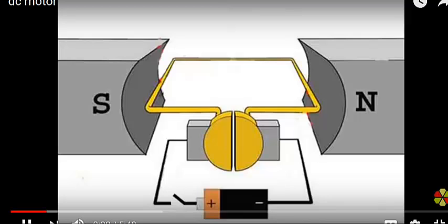Now here's the motor. It's kind of like the one I made in class. What you have is a battery, and then you come in with the wire to this thing. These are the contacts that I had. And if you remember, when I handed around the armature, it had copper contacts, and the shaft was copper. So you have physical contact here, which allows the current, the electrons, to flow from the stationary part to the moving part of the motor.